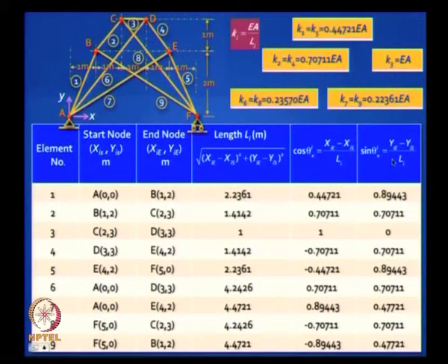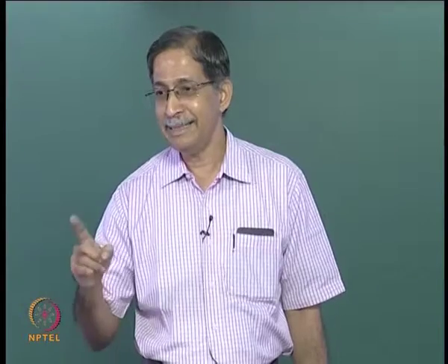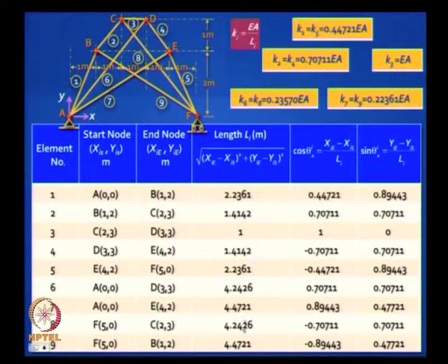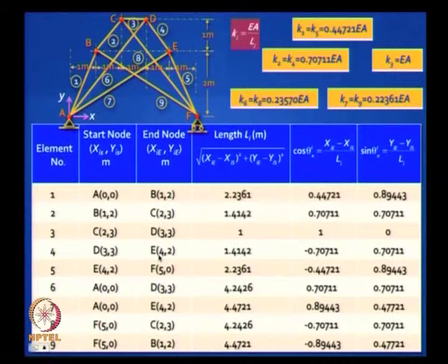With this information, can you fill in the TDA matrix at least for element 1? For the first element, fill in the TDA matrix, and by the way you can also get the axial stiffnesses because it is given by EA by L. L you have got here, you have calculated L here, so it works out to these values here. Signs are interchanged? The fourth one, cos theta should be positive. Wonderful. Cos theta for the fourth element.